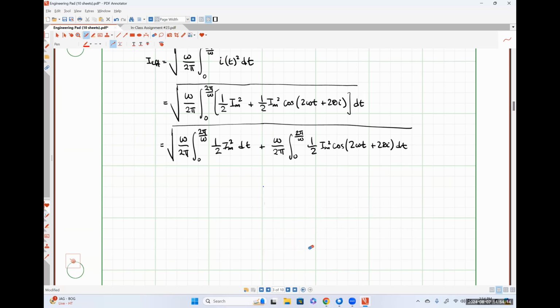So that convoluted explanation is why we get to say this whole thing goes to 0, because we are integrating that AC double frequency part over exactly 2 periods of that sinusoid. So all we're left with is this bit over here on the left-hand side, which is all constants, which makes our life way, way easier, okay?